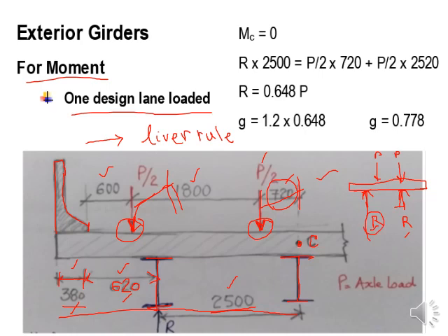That's why we have considered the pivot point as the first interior girder, so that all of the loads or the reactions will be passed through it and the unknown will be on the exterior, because this analysis is for the exterior girder. So we need to see the effect of the load applied just near the curb and the barrier. What is the effect of all of this loading on the exterior girder? If it were an interior girder, it would be okay, half from this side, half from this side. But for the exterior, this is an unbalanced situation.